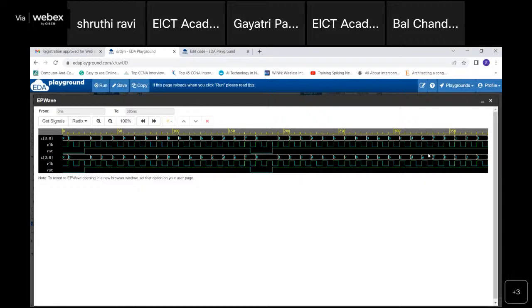So this is present over here. The simulation duration value we have given, but it is taking the maximum it can fit in, so only that much will be displayed. So this is how the counting takes place. It's a simple up counter, but built using the SystemVerilog dynamic array construct.